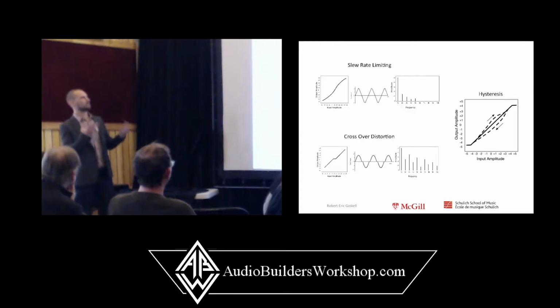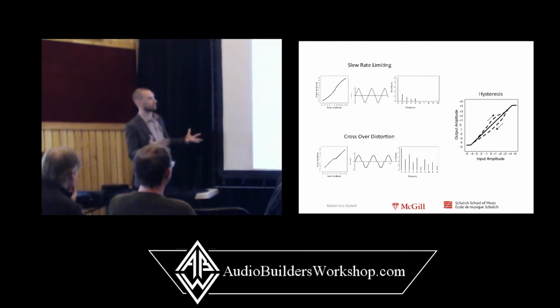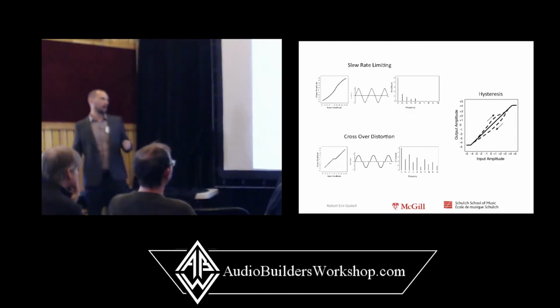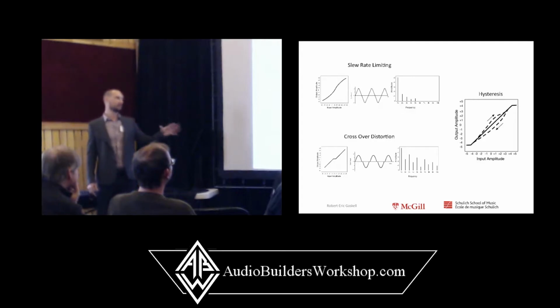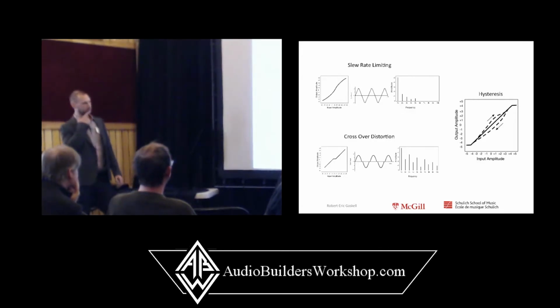I did a lot of listening tests in a past life on distortion. I think that hysteresis is a very salient effect. I think it makes the distortion more obvious than if the hysteresis were not there. So that'll happen in capacitors and transformers. They'll have slightly different distortion characteristics.